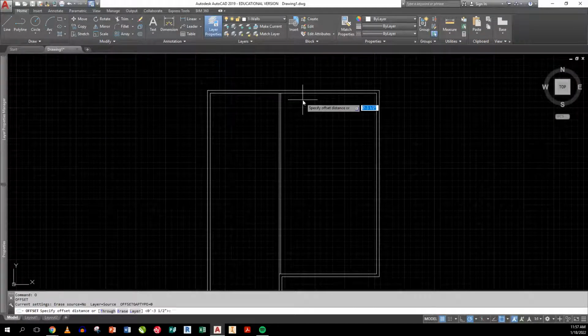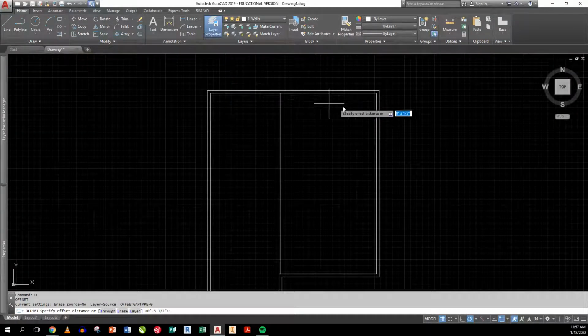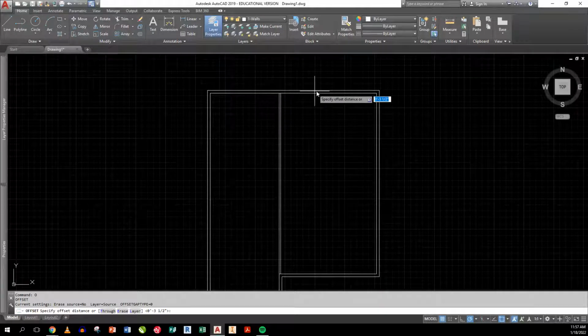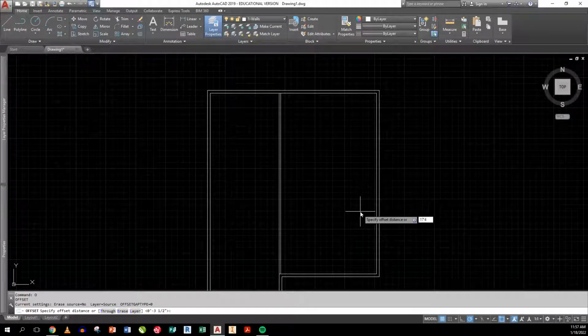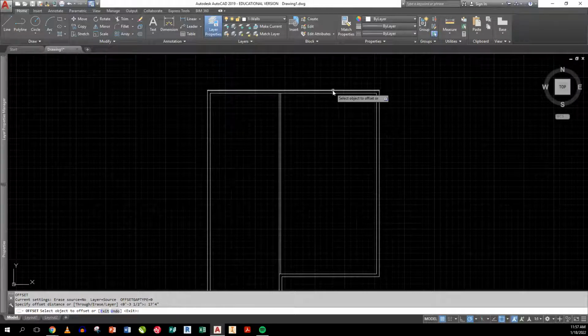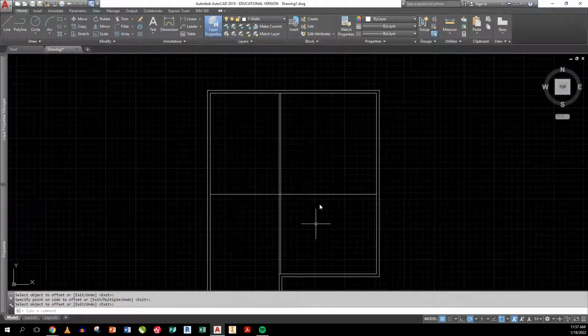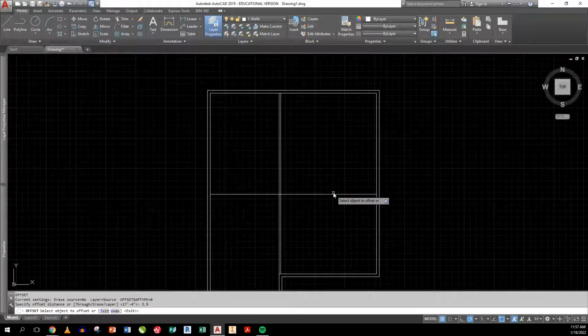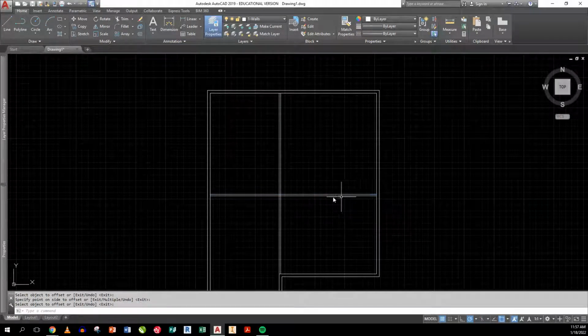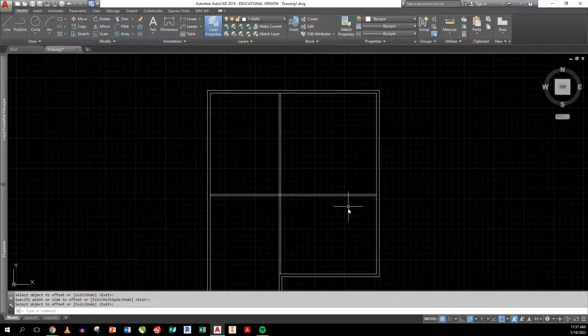I can go offset from here. I know that the kitchen dining room area, which is actually over in this part, from it to the pony wall that sticks out, there's a screen wall right here, is 17 feet 4 inches. If I offset from here out like that, I get that wall. Now, that's a line right now, it's not a wall. So I have to offset, again, 3.5 inches to establish the wall. Now, what's interesting is here, at no point do we tell how far out from this wall the cutoff is, but we do know it comes across this way. And if you look at the plans that we've supplied, you'll be able to figure that out.